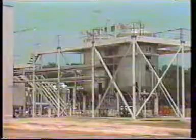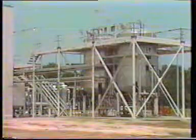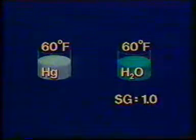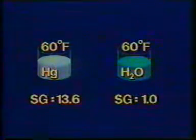Another term that's commonly used to express the density of fluids is specific gravity. Specific gravity is simply a ratio that compares the density of a fluid at a specific temperature to the density of either water or air at the same temperature. The resulting value is dimensionless. That is, it has no units associated with it. It is this quality that makes the specific gravity of a fluid so useful, since it can be used as a factor in combination with measurements in any unit.